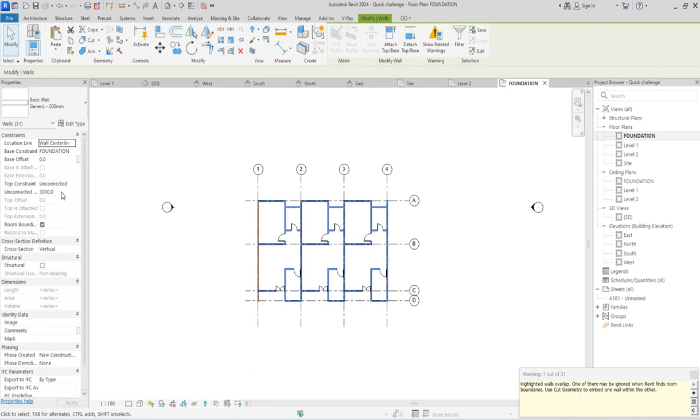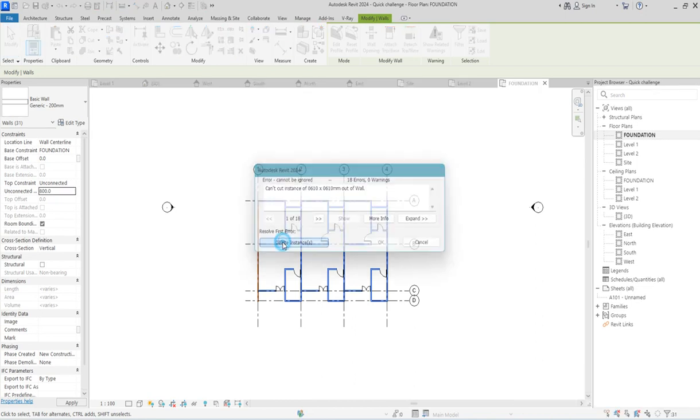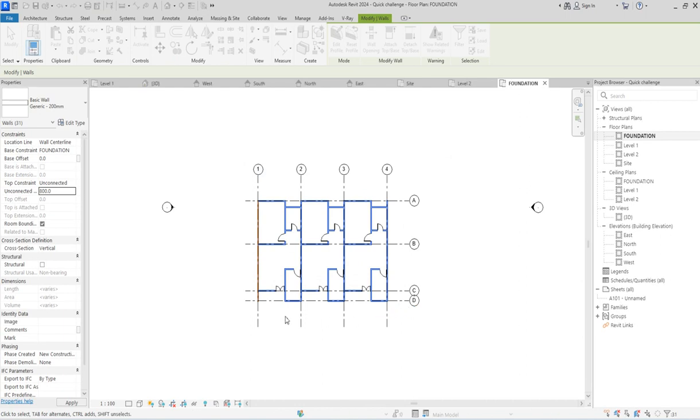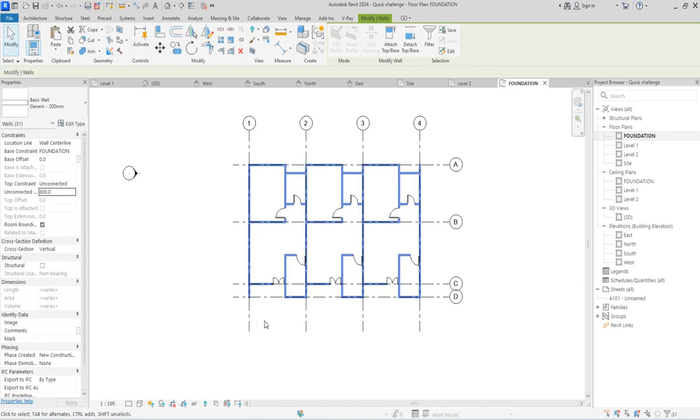So what you do is change the connected height here. You should have 1 meter of height. The slab takes 200 millimeter, so what you are left with is 800. That will be the height of the whole wall that you're going to be seeing. So delete all instances, as it's giving you the errors. Delete those instances. You don't need them.